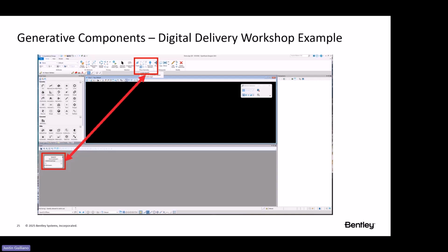So for example, the downstream GC workflow, this is where you would have an offset coordinate system that is relatively the negative XY value of your project coordinates. That way, when you reference your DGN in, you're linking it to that offset coordinate system so that the file comes in at the origin. GC doesn't like really big values for X and Y. It starts to get really wonky as you get further away from the origin. So what this does is it facilitates GC by bringing the model to your origin. And then from this, you can export it back out from the base coordinate system. So it puts it back in the proper location.